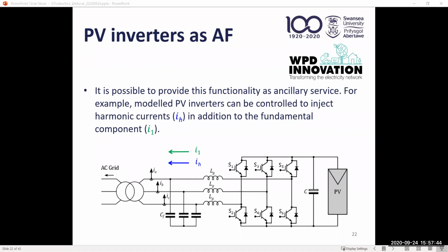However, I think the general application of this is not really to cancel out each other's harmonics, but mostly to cancel harmonics coming from the loads, so existing harmonics on the system. In terms of canceling each other's harmonics, I don't think that has been done, because it would be a challenge to have the measurement points, since you really cannot monitor all harmonics from all the wind turbines. So what I know, the typical application is to cancel harmonics outside the wind farm.